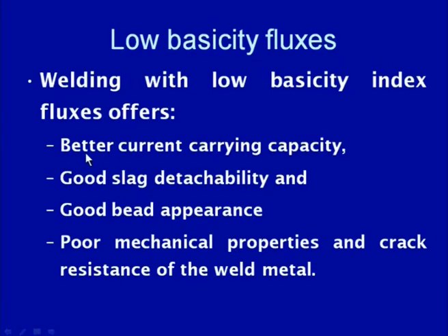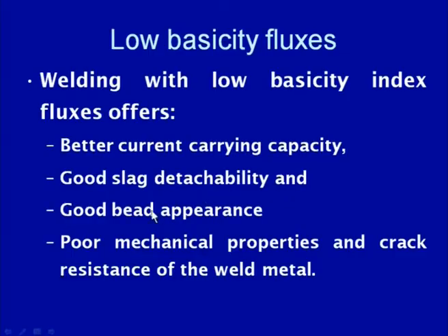So, out of these, if we see, low basicity fluxes help in having better current carrying capacity, which means this can allow a higher flow of current through the electrode, and the welding system can work with a higher current, and the slag detachability and the bead appearance are also good.